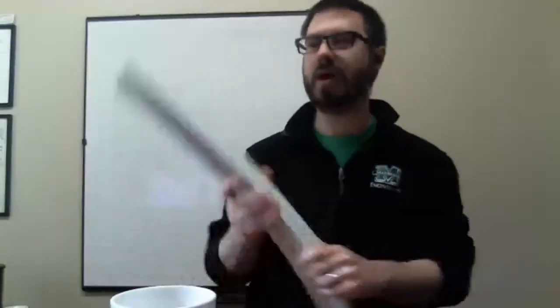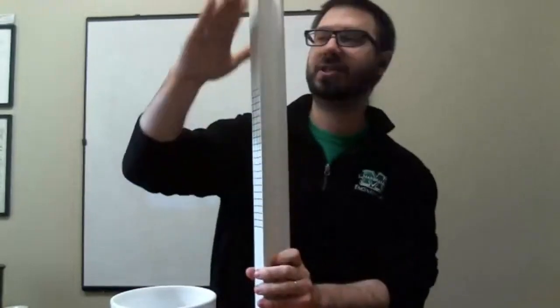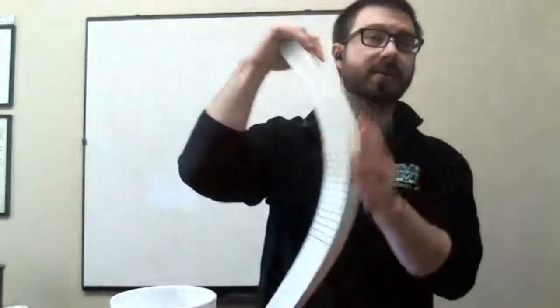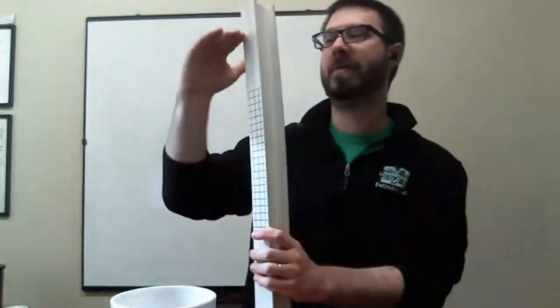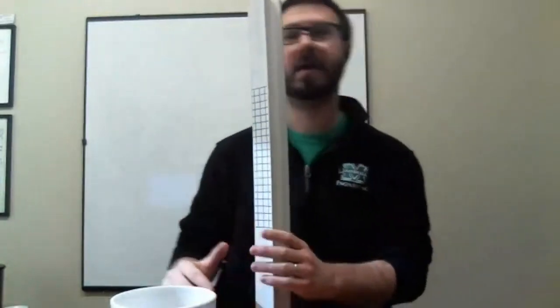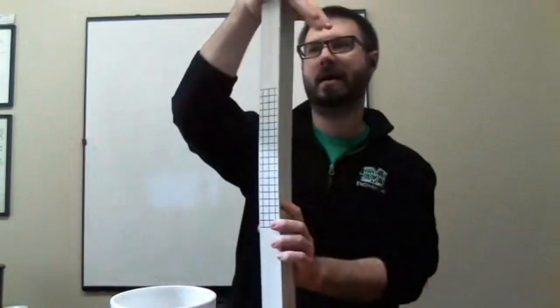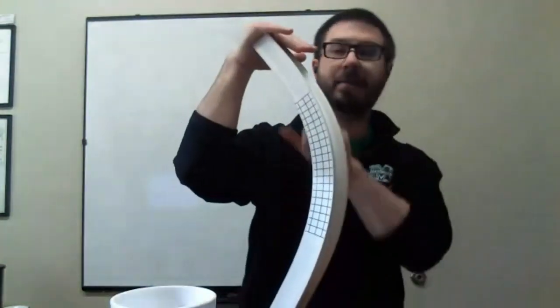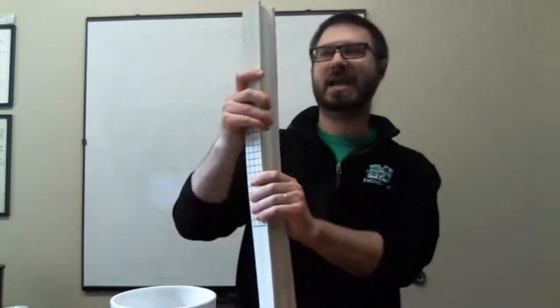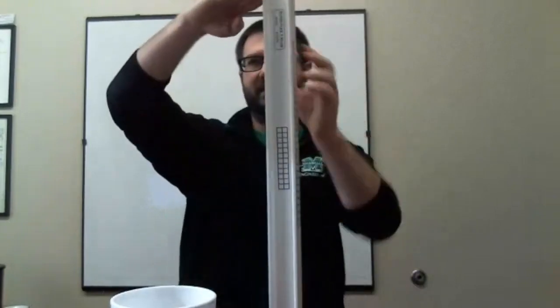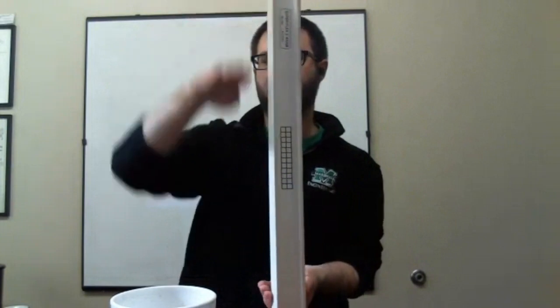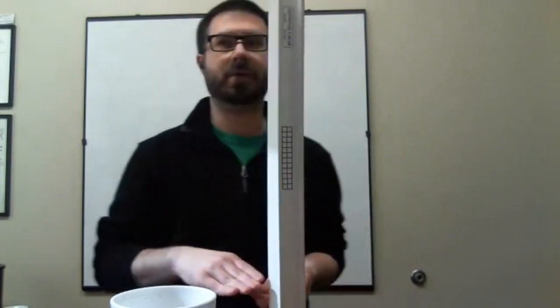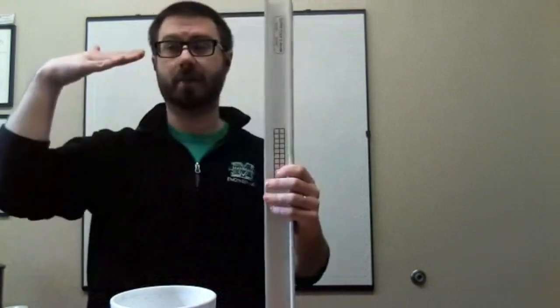For each of those limit states, I might compute a capacity. What is the capacity of this element before it buckles? Or what is the capacity of this element before it reaches its capacity under yielding? I've got these two. For this element, I would argue that its buckling capacity is probably lower than its capacity under just yielding. But that might change if the column was, instead of this long, this long. What if it was a really short column? Maybe that short column wouldn't buckle.